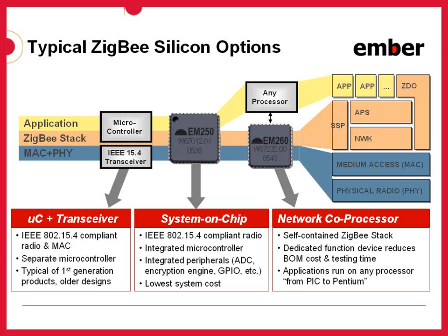Using a proprietary serial protocol over one of these interfaces, the host microcontroller can interact with the stack, potentially abstracting these serial transactions into a library or operating system module that better accommodates the needs of the application running on the host. This model allows for great flexibility on the application design and the host processor architecture, and it allows the application designer to ignore many of the implementation details about the stack itself.